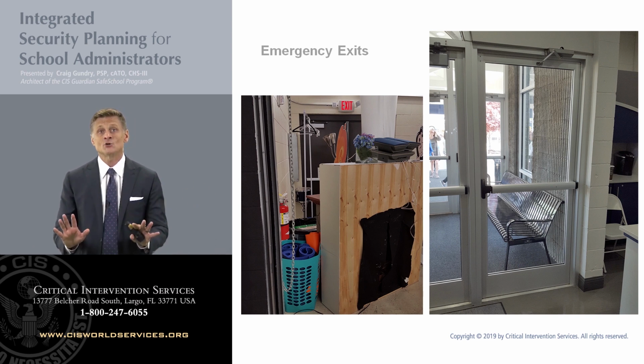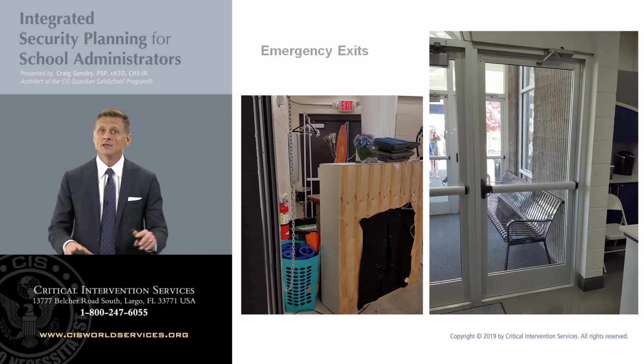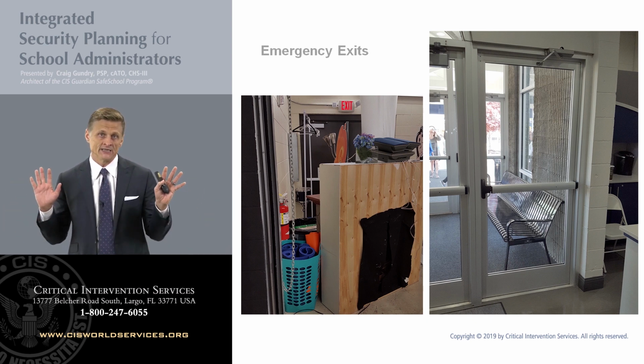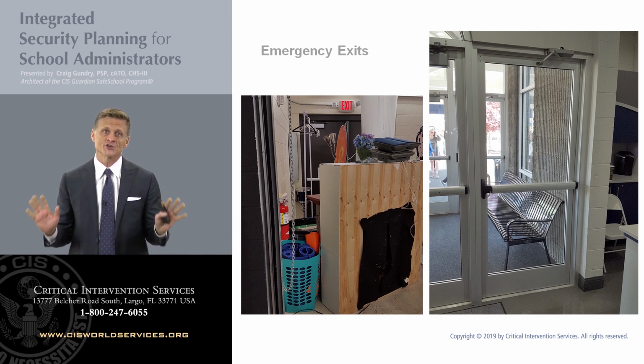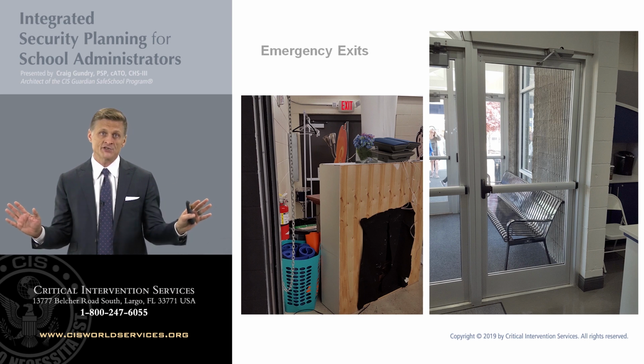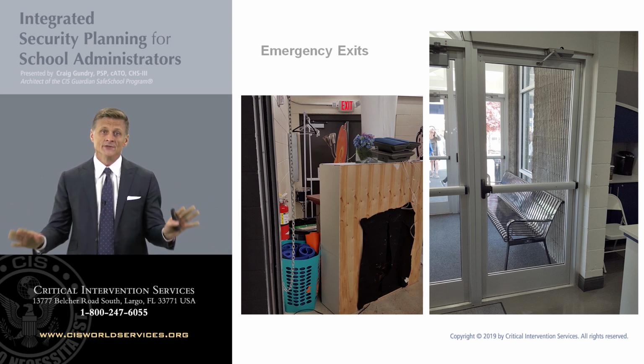Well, again, if somebody is trying to egress under high stress conditions and they run into this lobby, they're not going to be able to quickly and intuitively distinguish which doors actually can be used to escape and which can't. And if they run to one of the exterior doors to the left or to the right, they're going to be greeted with a locked door, or if it was unlocked, they'd be greeted with a bench on the other side.